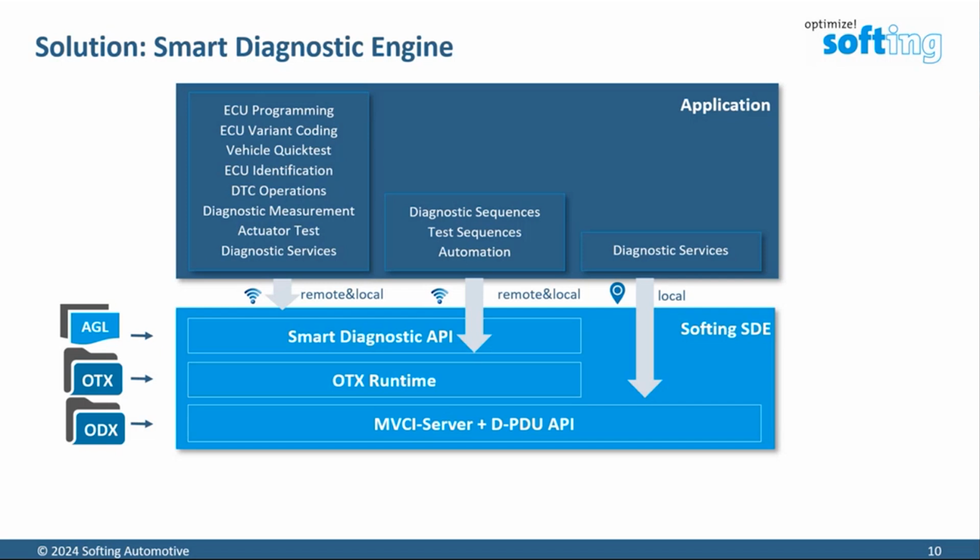It means, for instance, when wanting to read a measured value, the programmer no longer needs to know the diagnostic namings, service name and format, which differ for each ECU and each value he wants to read. He can simply ask the SDA for the available measured values, always using the same method. It is not data dependent, and schedule then how often he wants to receive an update. He no longer needs to be an ODX or MCD specialist to do this.